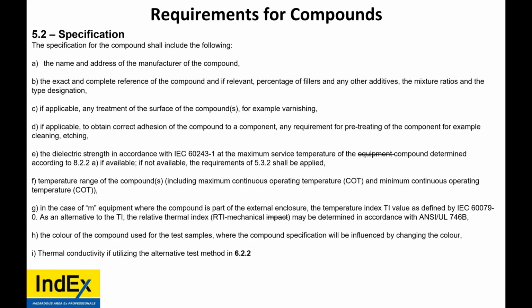So the specification for compounds, well, it says you have to have the name and the address of the compound manufacturer, the exact and complete reference of the compound, percentage of fillers, any treatment required, how to obtain the correct adhesion, the dielectric strength, the temperature range, the external enclosure and temperature, the color of the compound used for testing, what color it changes to, and the thermal conductivity. There's a lot of things involved.